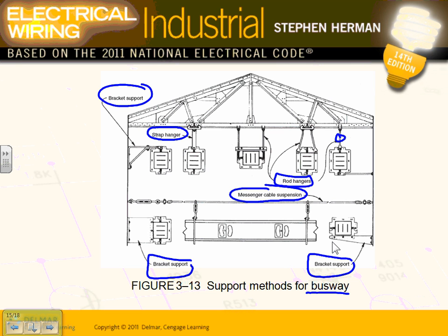When we deal with our project, our manufacturing floor, all this owner equipment that I gave you a list of is going to be tied directly from the plug-in busways. You're going to use a feeder busway, plug-in busway. A lot of companies, guys, if you have a 4,000 amp switch here and you have the transformer sitting outside, instead of pulling 12 runs or 11 runs of 500 kcmil each set, they put a 4,000 amp busway directly from the transformer all the way to the building. Of course, if it's outdoor, it has to be in an enclosure that's rated for outdoor location.